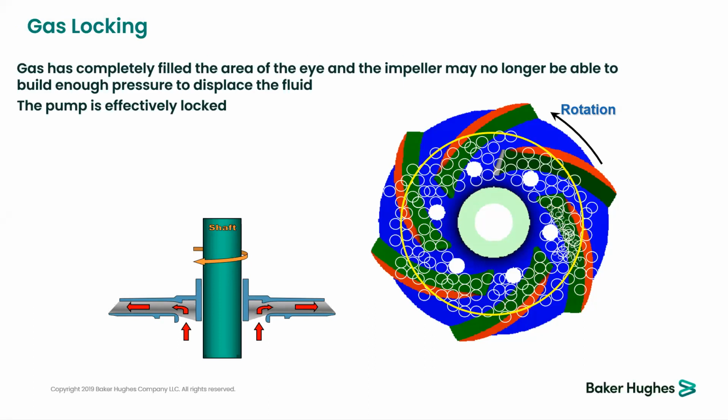When enough gas is present in the impeller, the gas will tend to accumulate even more near the eye of the impeller, because centrifugal force sends the higher density liquid to the impeller outer diameter, while the gas stays inside near the eye. At some point, the gas obstructs the eye completely and no longer lets the liquid enter the eye.